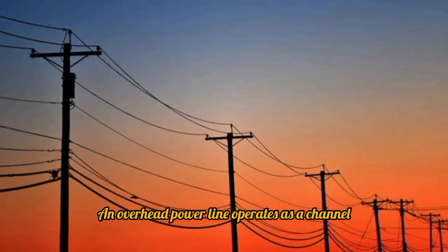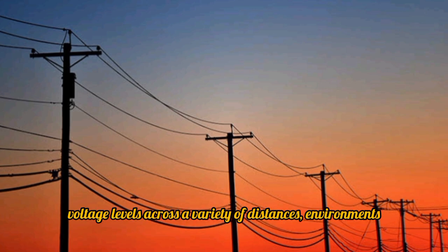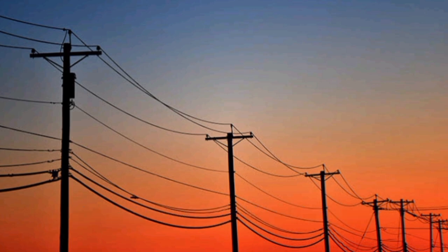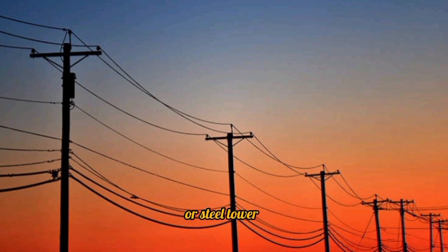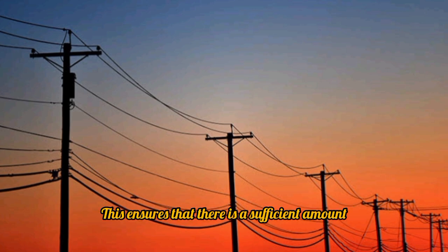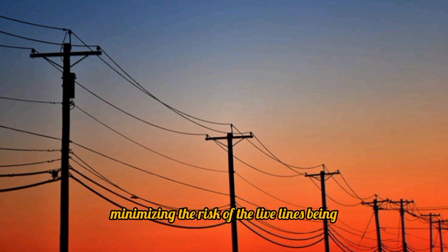An overhead power line operates as a channel to transfer electromagnetic waves of varying voltage levels across a variety of distances, environments, and landscapes to supply electrical power where it is needed. Power line cables are structurally supported by utility poles or steel towers, which are designed to keep the lines suspended at a safe height. This ensures that there is a sufficient amount of ground clearance, minimizing the risk of the live lines being disturbed or damaged.